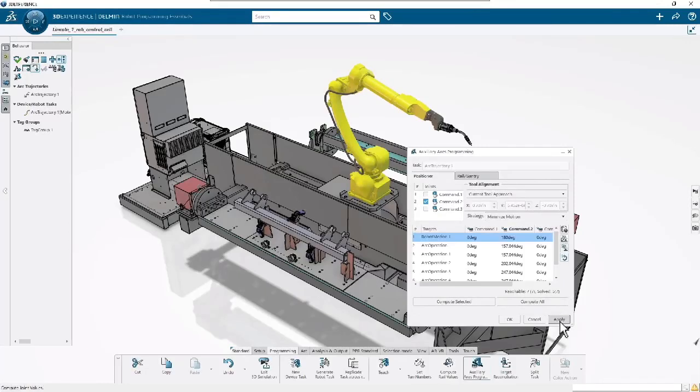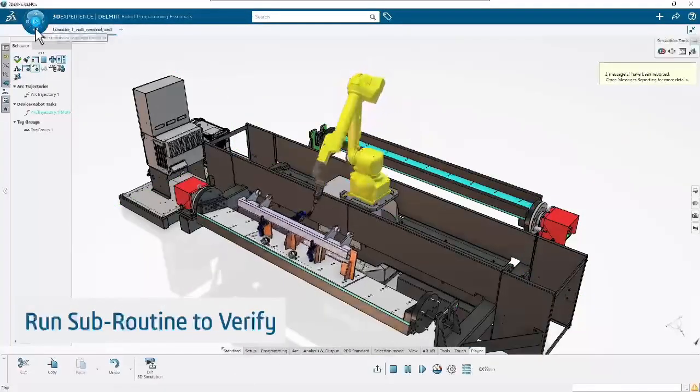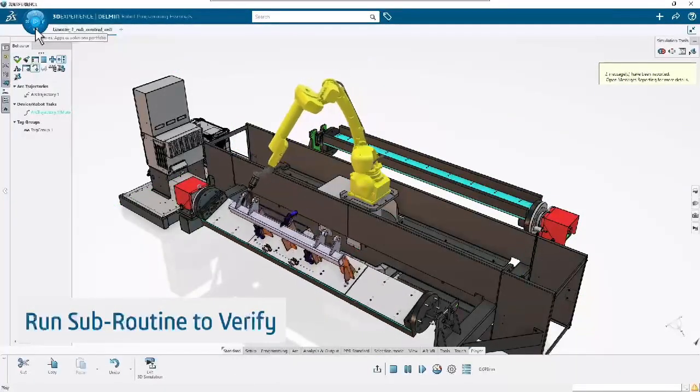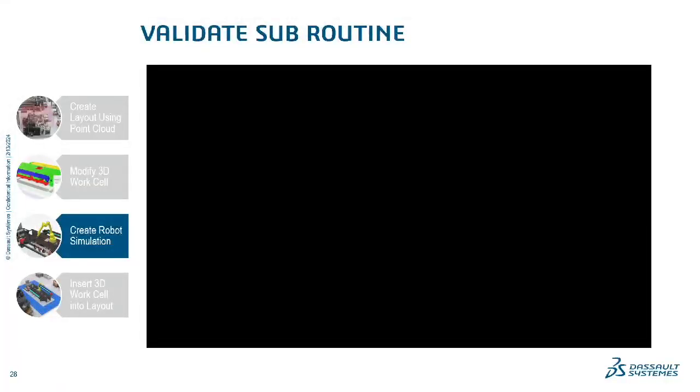By default, it put it downwards. So change those values, hit compute, and when I replay the subroutine, you can see that now the positioner is moving the workpiece so the robot doesn't have to work so hard. Really useful when you have arc trajectories because it makes it so that the robot's not trying to get in those nooks and crannies all by itself.